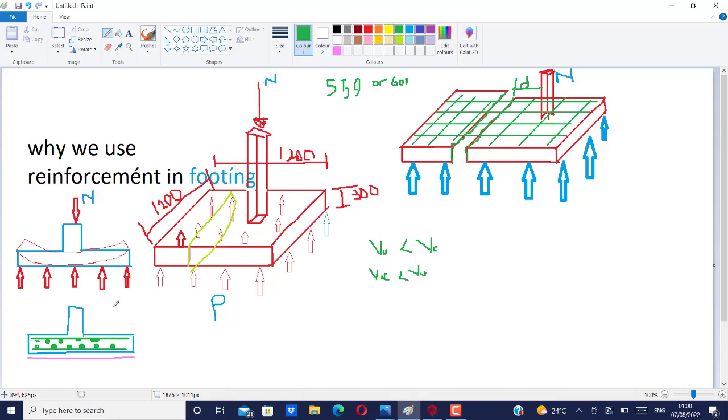So most times when you see a footing that is not a combined footing, and you are seeing the footing carrying both top and bottom reinforcement, you should know that this is a situation that has occurred, and the designer is trying not to go further by providing this.